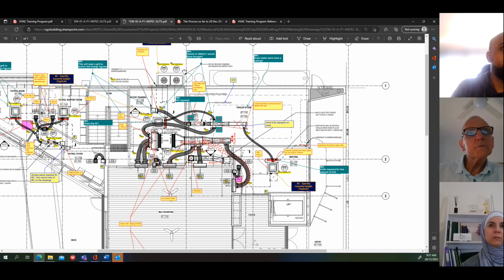I didn't mention, but I'm sure you're aware that if you look at a dimension on a duct, so there's 600 by 450, what does that mean in terms of what you're looking at? Well, it's 600 wide. So as you're in plan, it's 600 wide and it's 450 high, in depth of the plan. Okay.